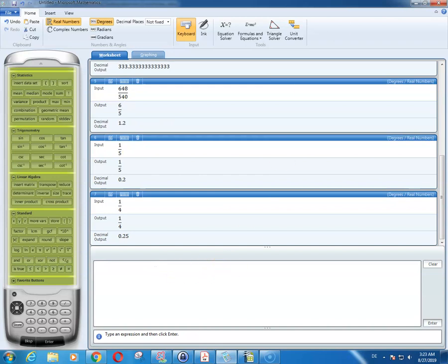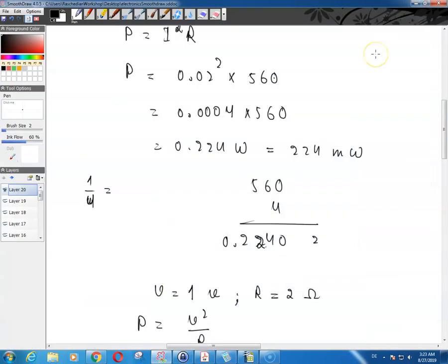For example, if you choose a 1/4 watt resistor, that should be enough for this circuit, or greater than that, but for this circuit I would choose a 1/2 watt resistor or so.